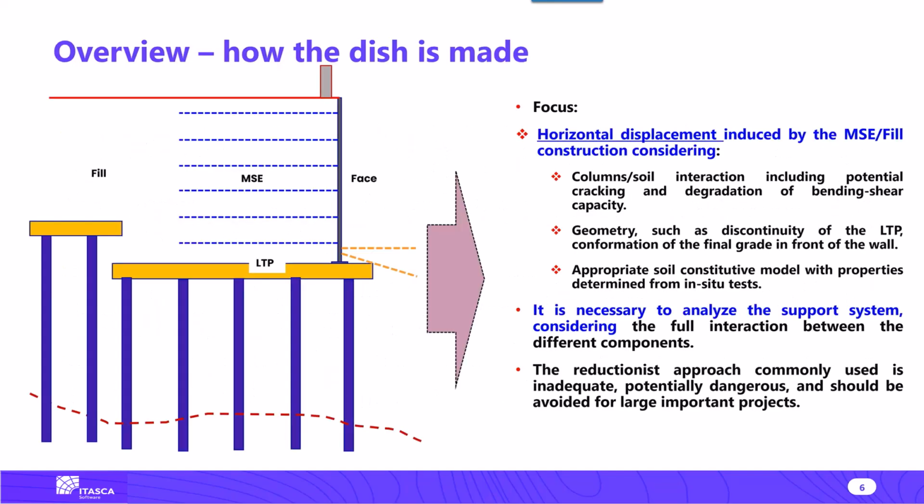Okay, so this is just a cartoon view of our typical configuration for supporting ground improvement, with an MSE wall and concrete facing. I'm emphasizing again that the main focus of this system should be toward horizontal deformation control. The vertical settlements are typically covered and satisfied; there isn't really much of an issue. Most of the time, when the system fails or is not performing well, it is because there is some problem in the horizontal direction.